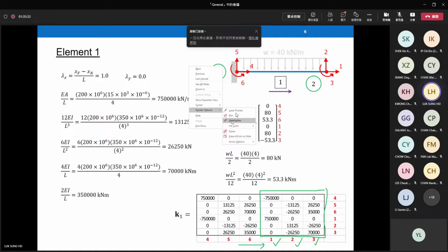You can treat this as something like a fixed end beam. Find the corresponding fixed end force and fixed end moment. In topic 2, I showed you 2 pictures. One is for UDL, the other one is for point load at midspan. Right? I only assess you on these 2 scenarios for intermediate loading.